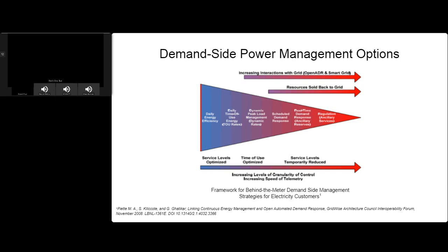The first and foremost thing is to operate your data center as efficiently as possible. If you look at the historical trends of power usage effectiveness, or PUE, we have come from 2+ PUE to almost 1 point something, or even lower than 1.1 PUE. What does it tell us? It tells us a couple of stories. One is that data centers are doing a great job on improving energy efficiency, which is basically getting the same level of service while using as little energy as possible. The second thing it tells us is that a lot of improvements have happened on the infrastructure side of things, specifically with the cooling side.